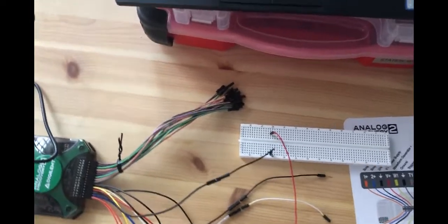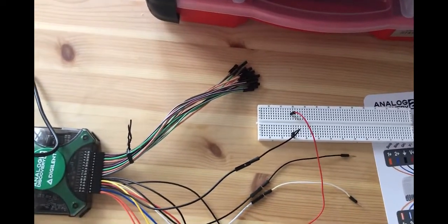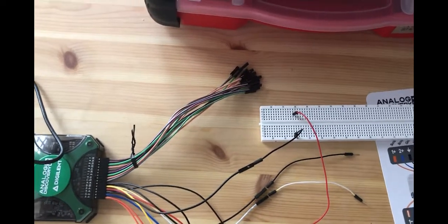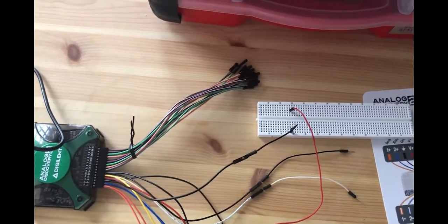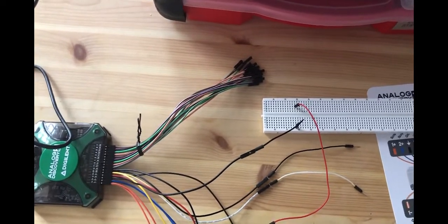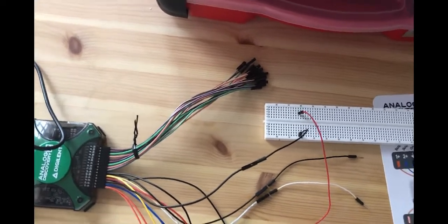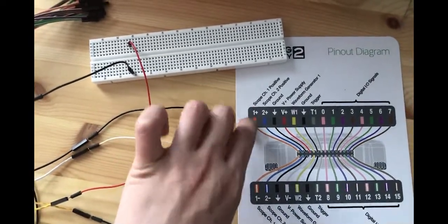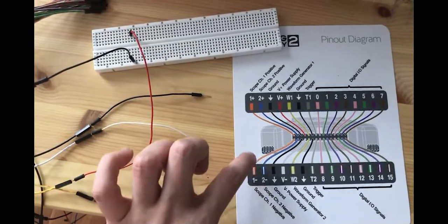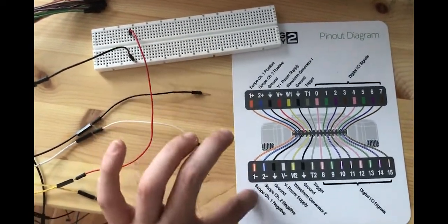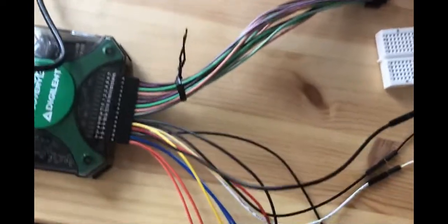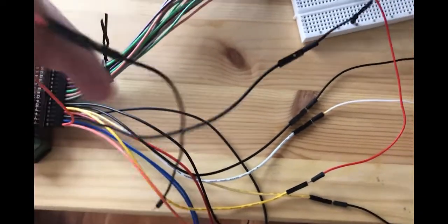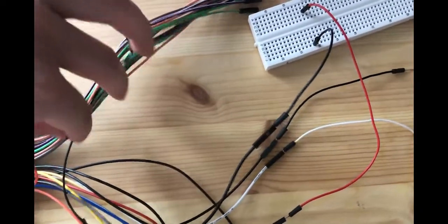If we want to see the signal, because we want to verify it, we need to connect the oscilloscope. Either we use the multimeter, or we use the oscilloscope. We need to use the oscilloscope cable, which has been labeled here. You see channel 1, the positive of the oscilloscope channel 1 and the negative of channel 1. So I choose the first channel, and the positive is going to be the yellow one without a strip.